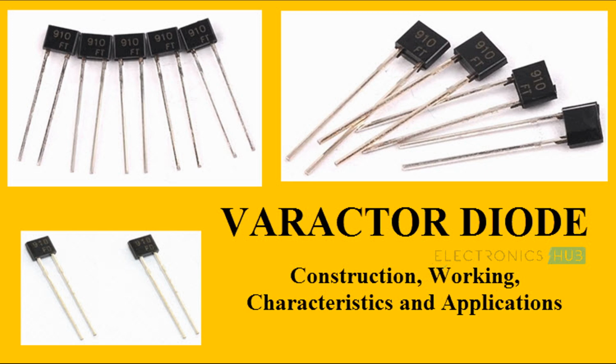Varactor diodes are used in electronic circuits for voltage-controlled tuning, frequency modulation, and voltage variable capacitance applications. The primary characteristic that sets Varactor diodes apart from standard diodes is their ability to vary their capacitance with applied voltage. When a reverse bias voltage is applied to the Varactor diode, the width of the depletion region, the region without charge carriers, at the p-n junction increases, resulting in a change in capacitance. The reverse bias voltage directly affects the width of the depletion region and, consequently, the capacitance.